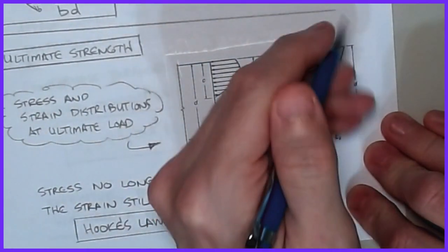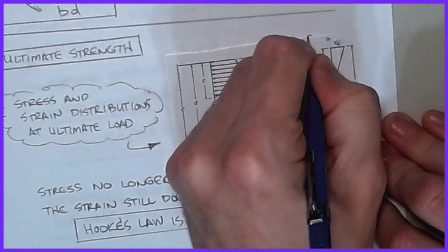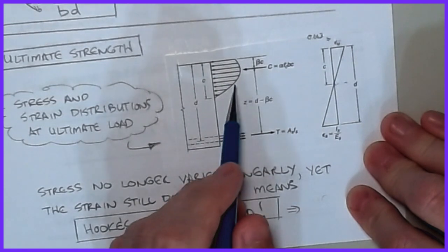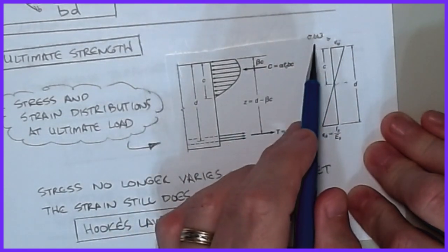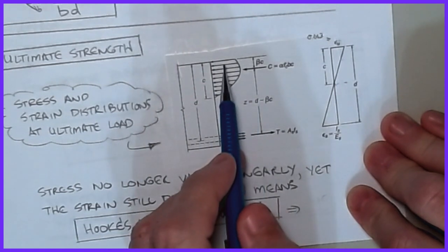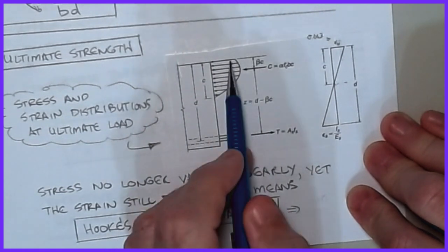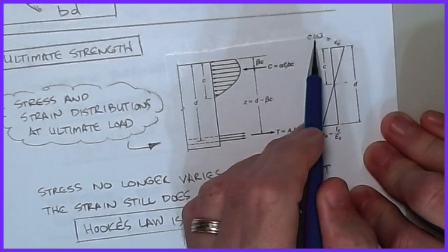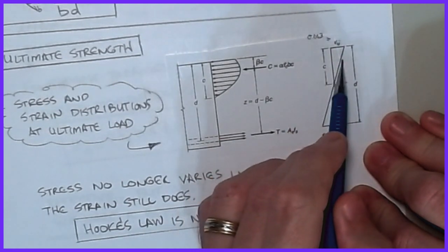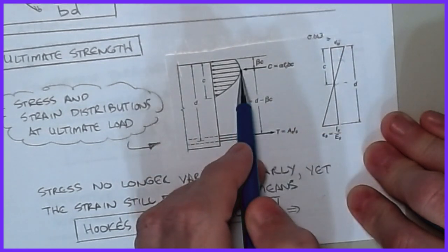But remember, now we're prescribing that the strain at the top is 0.003, the limit of the strain. From our material research, as we get to strains higher than about 0.002, the stress in the concrete corresponding to a strain of 0.003 is different than at, let's say, a 0.002 strain. I have a higher stress possible on that.